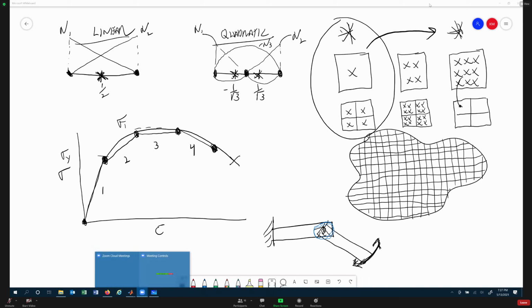Okay. So kind of curious, I just want to poke at this. So there's no way that you can combine linear and quadratic in the case of that beam that you showed, if you're interested in that region? No, it depends. It depends on the software that you have. Some software won't let you mix element formulations. I've heard of it in a part. As long as you change the element density, they usually let you change it within that density. But it depends on the code that you're using.